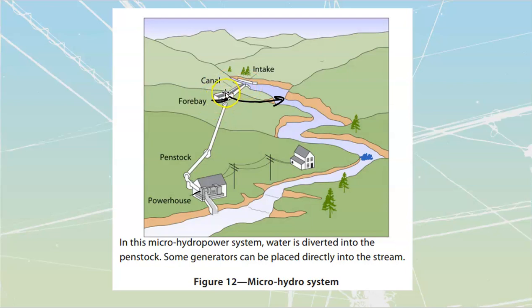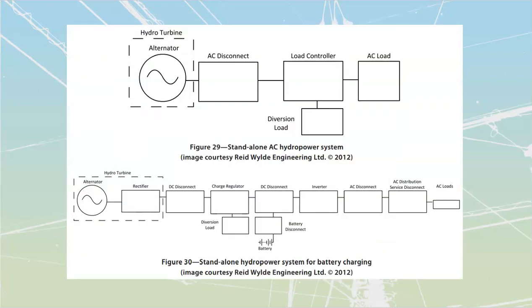And as long as we maintain pressure, we know what it is because we can calculate the drop over here. We can calculate the frequency that we are going to have. So my speed stays the same because it's all based upon how far this water is falling down that mountainside over there. Through the penstock, obviously, we're not running this thing wild.